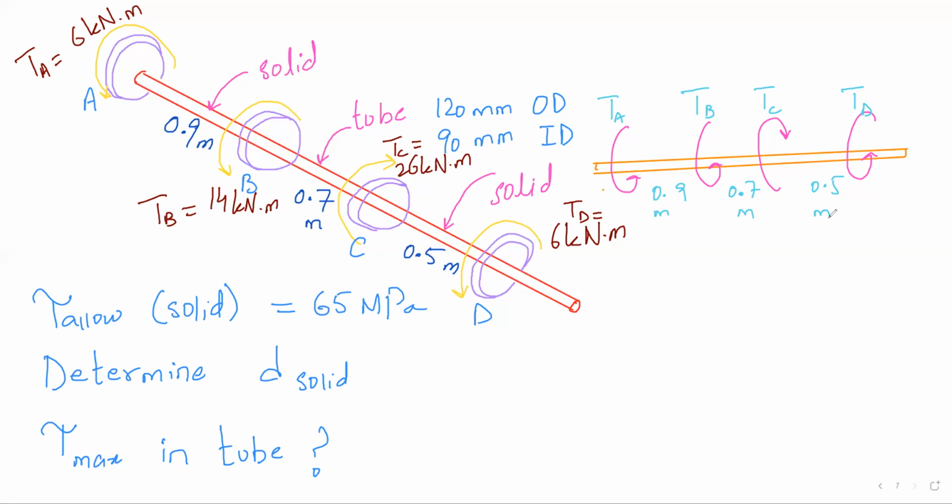Once you know the shear stress, for example, we have a graph like this. I understand your question. It will start from here, the shear stress lines keep on increasing for a particular torque. This means that the maximum shear stress that the object can sustain is this value. Of course, the torque is already fixed, so the only thing that you want to play with is the diameter. You really don't want a big diameter, because if your torque is fixed, you have a certain value. We don't know the solid diameter.